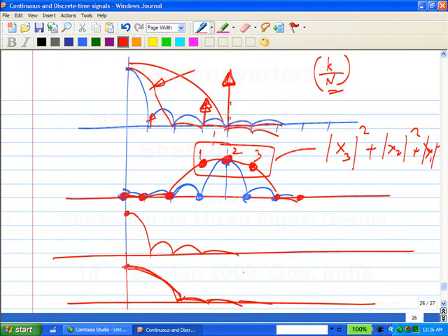Now, this Hann window, what are the other things? Yeah. And you can implement it in... Pardon? You can implement it in... No, these are usually used only for analysis, right? For instance, if you want to analyze the data coming out of an A to D, you still get the samples that you get. And this multiplication by the Hann window and all that is happening in MATLAB or whichever software you use to analyze.